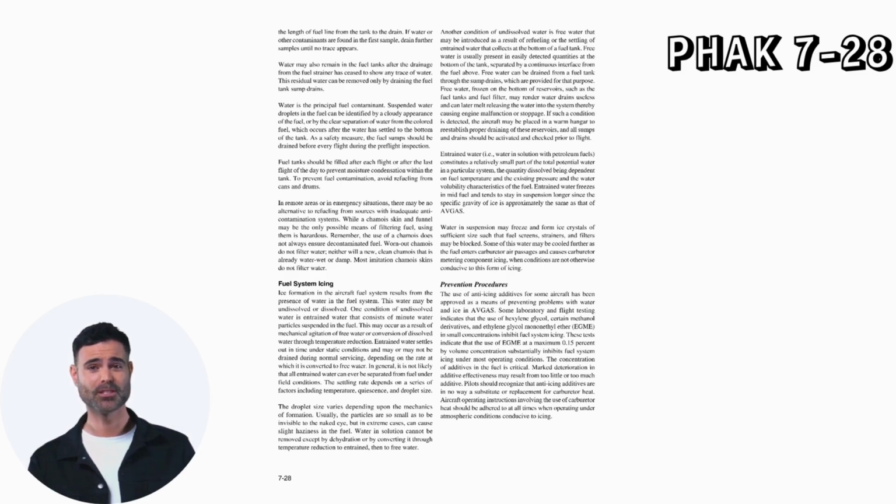Entrained water freezes in mid-fuel and tends to stay in suspension longer since the specific gravity of ice is approximately the same as that of AV gas. Water in suspension may freeze and form ice crystals of sufficient size such that fuel screens, strainers, and filters may be blocked. Some of this water may be cooled further as the fuel enters carburetor air passages and causes carburetor metering component icing, when conditions are not otherwise conducive to this form of icing.